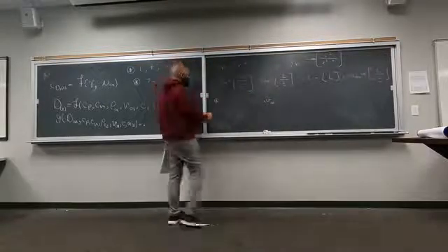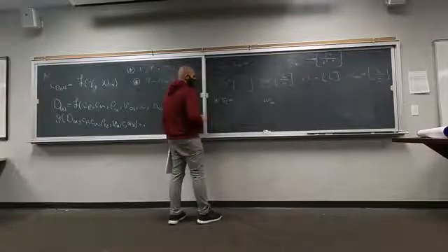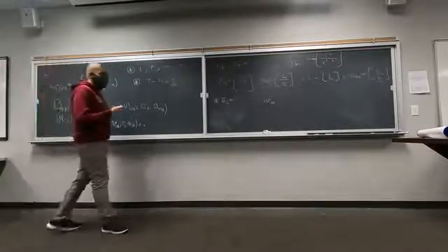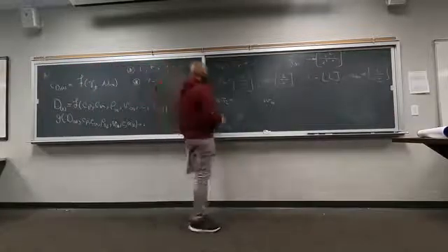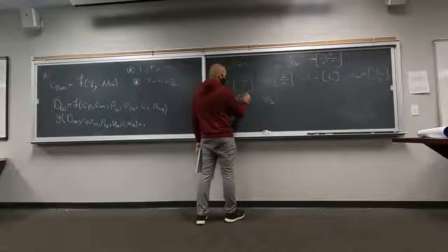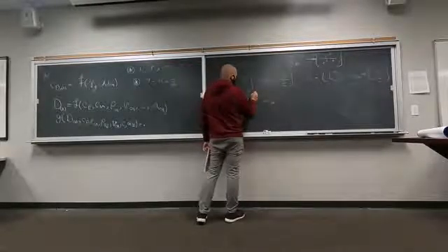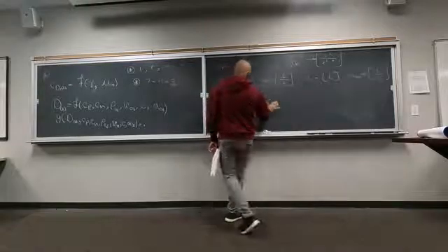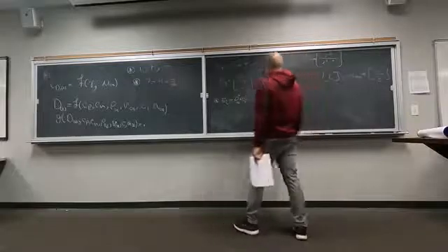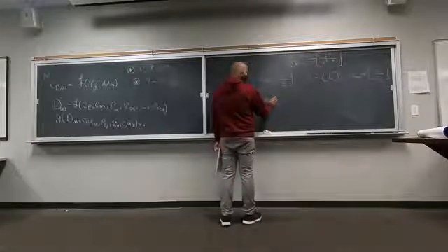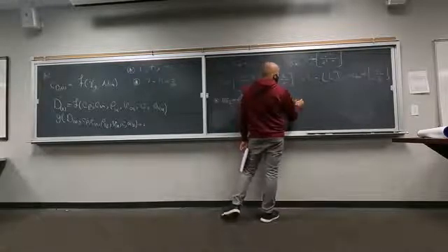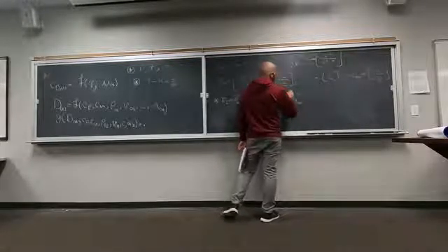And then the idea was this pi, let's call it pi 2, because we did pi 1 in the previous lecture. This pi has to be a multiplication of all of the independent variables here. So rho infinity to the power a multiplied by Cp to the power b multiplied by Cv to the power c multiplied by, what else do we have? V infinity multiplied by c to the power d and multiplied by a infinity to the power e.